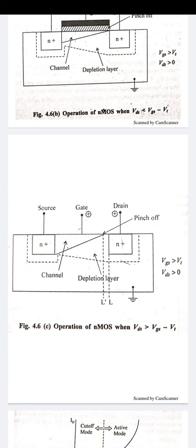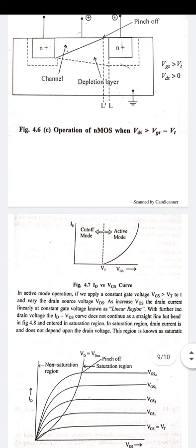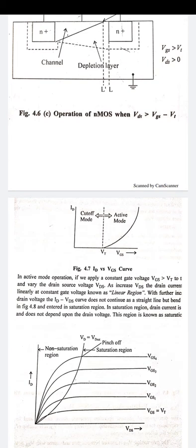So basically we have shown here the two types. When VGS is less than the threshold voltage, no channel layer exists. The two regions are physically separated from each other, with no direct current flow between the drain and source. That is basically an open circuit between the drain and source terminals, where the drain current is 0. That is called the cutoff region of operation.